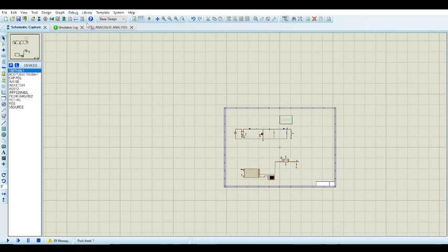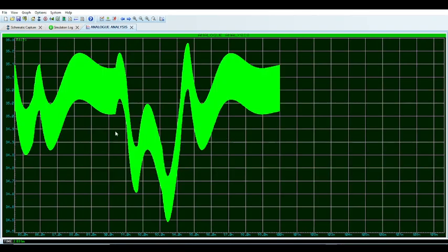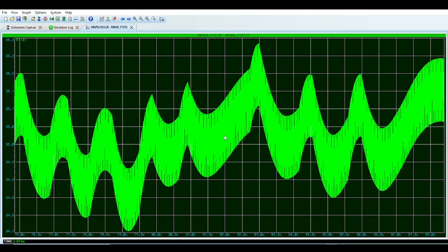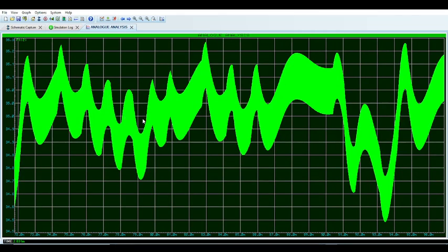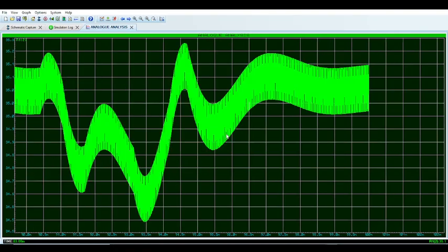So that's that. Let me just go there. Yeah, there you go. It's 35. As you can see, it's jumping up and down a bit when you zoom into it, but remember, this controller does not have a great PWM resolution. As you can see, for 100 kilohertz, it's 159, which is not a great PWM resolution. So you see, it goes like that and it jumps. Obviously, you can tweak the coefficients, etc., and make it a bit better. So the minimum here is 34.5, maximum is about 35.3. Yeah. There you go. And that's that.